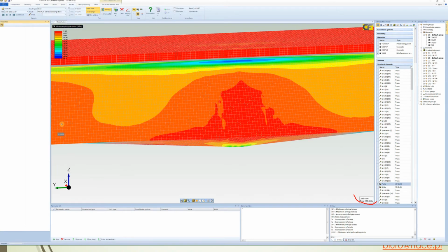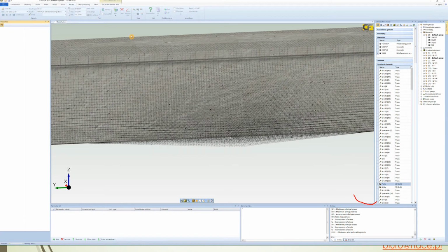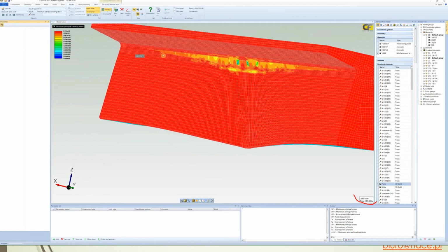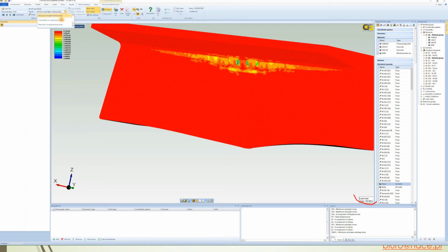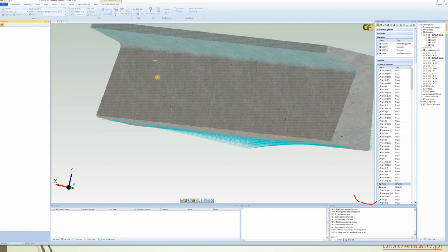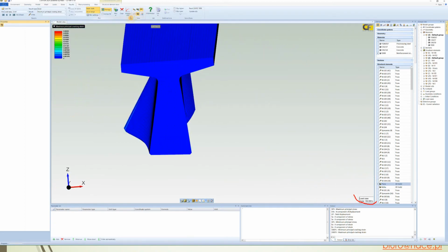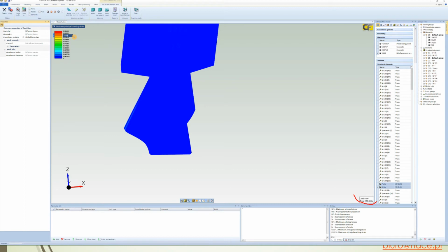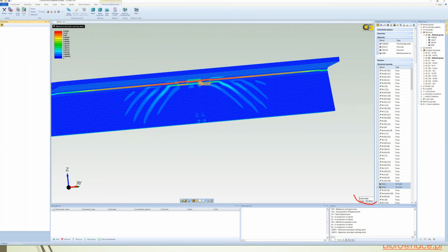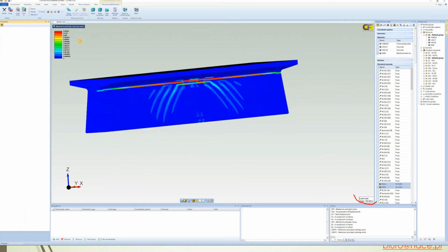And also for checking the cracking tension stresses, here we can plot the maximum principal stress, and here you can see cracking strains. The different principal cracking, the principal tensile stress, and also the cracking. If we plot cracking strains, you can see the maximum crack happens in the connection between web and flange. But we can modify the range because that is a huge crack, just to be able to appreciate the rest of the cracks. So modifying the range, here we can appreciate 45 degree diagonal cracks.